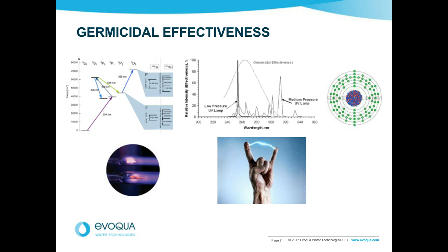If it's something we haven't done before, then we will gladly pilot. We have skid-based systems and container-based systems that we can deploy on a pilot basis, and we can then verify we get the performance we expect. So we have a lot of experience of monochloramine, trichloramine and other compounds. If the compound is large, with high molecular mass, they're generally pretty easy to break down with UV. The smaller ones are the harder ones because they are more tightly bound. So it's on a case-by-case basis. Yes, it can be done. If we haven't already done it, then we'd be happy to do a pilot.